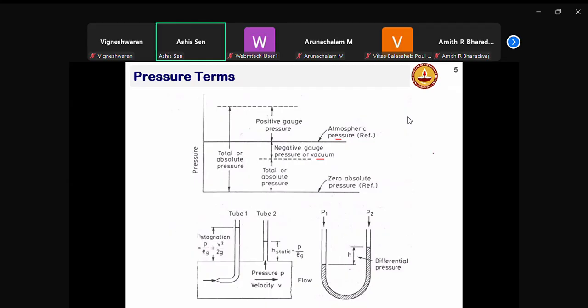Now, the different instruments that can be used for measuring pressure that we are going to talk about. You can use, this is called the pitot tube, okay, and this is known as the manometer tube, and here you basically insert into the tube the pipe in which the fluid is flowing by just creating a hole. And this would basically give you the static pressure, okay. This arrangement will give you the static pressure.